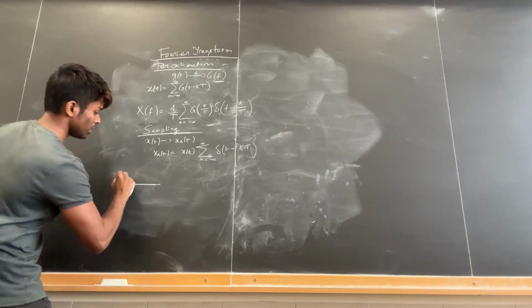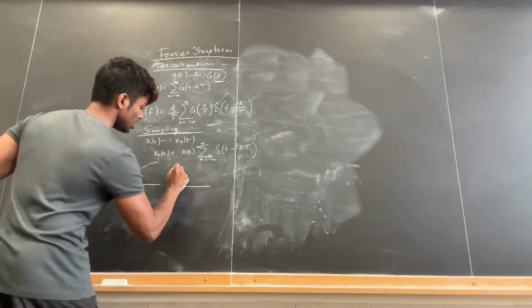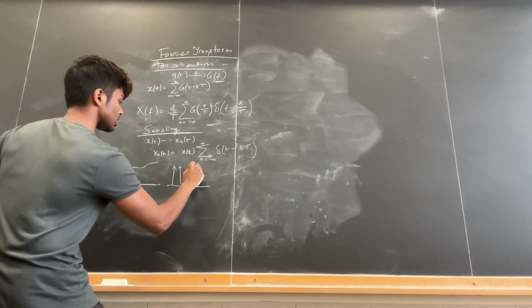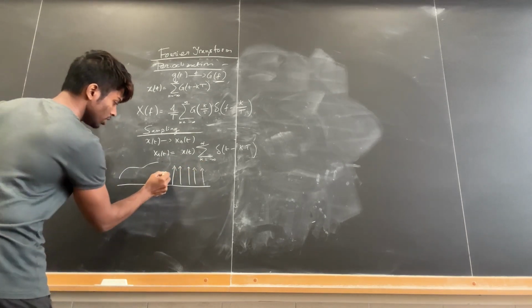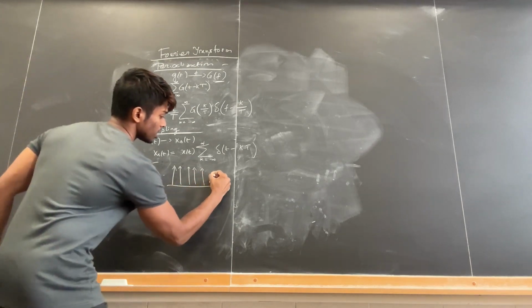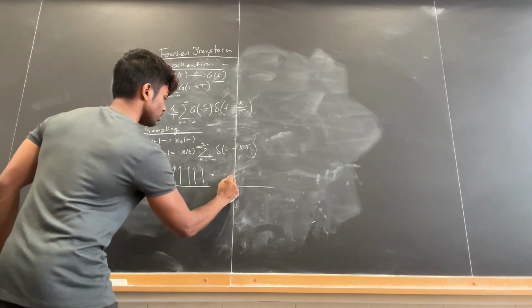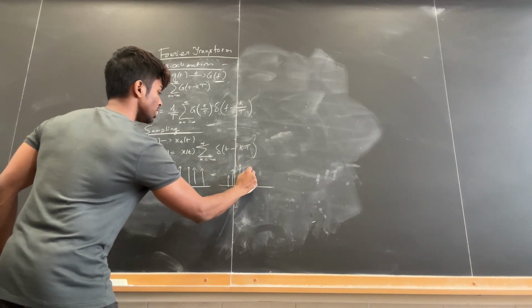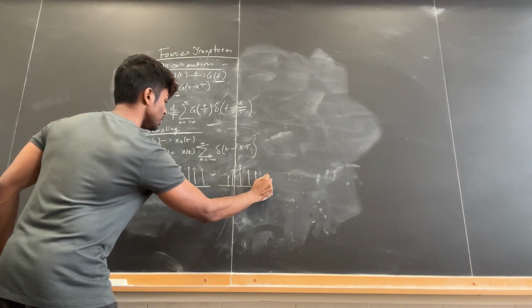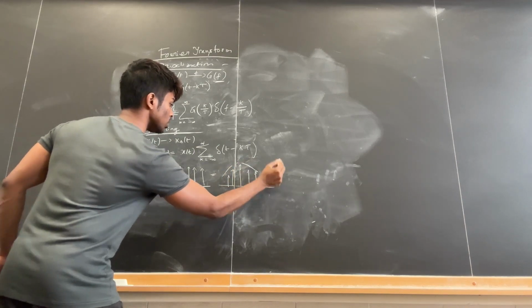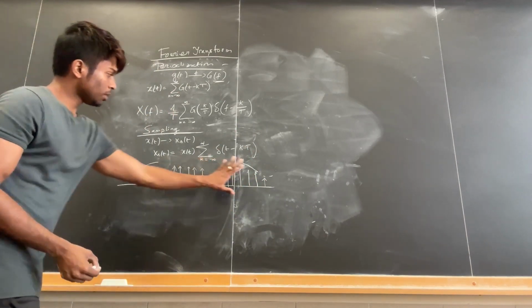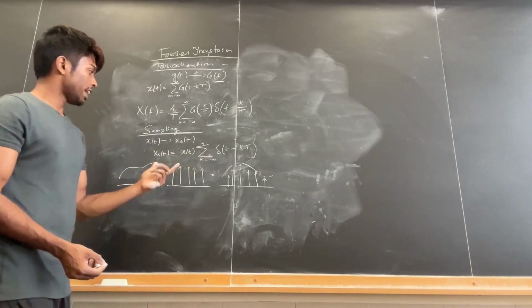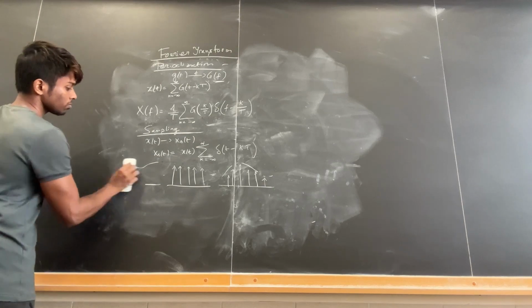The signal is something like this, and the impulse train is over a period of T like this. When we multiply the signal and the impulse train, it results in attenuated impulses at those very portions where the signal appears with some value. So that is the basic idea of sampling. We are essentially discretizing the signal, and that is what sampling is doing.